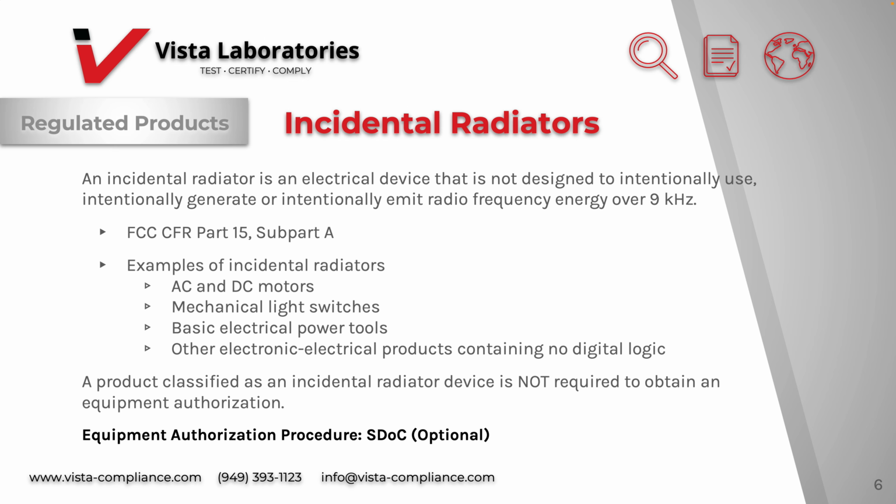These products are regulated under FCC Rules CFR Part 15 Subpart A. Examples include AC and DC motors, mechanical light switches, basic electrical power tools, and many other electrical products containing no digital logic. A product classified as an incidental radiator device is not required to obtain an equipment authorization. The equipment authorization procedure is SDOC. It's optional, but if in doubt, feel free to contact us and ask.